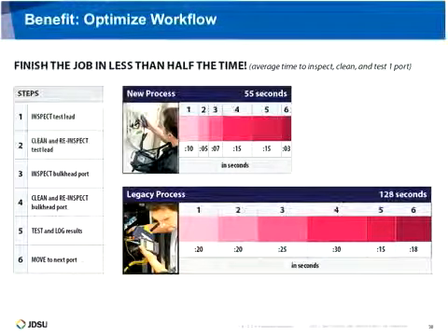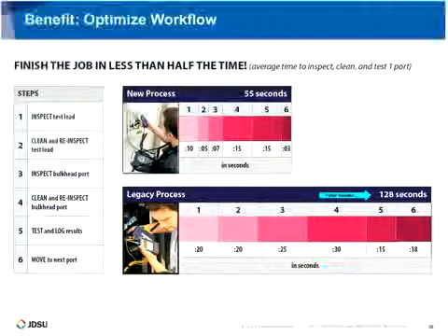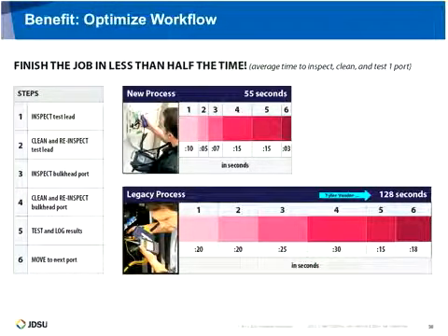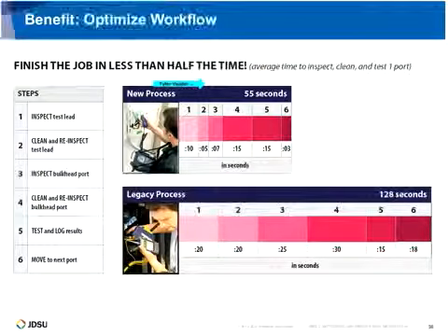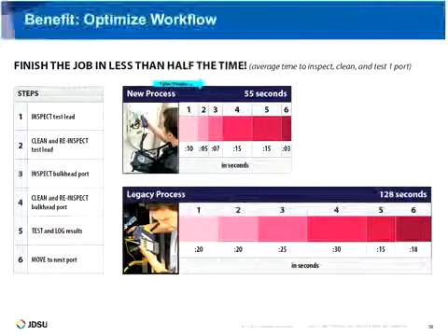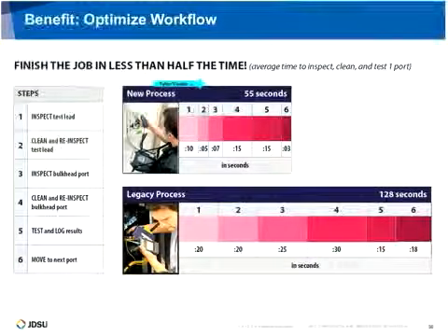The benefit of that, obviously, is that you can work a lot faster. The process that I described earlier of over 2 minutes, that's the old way of doing it. Contrast that with even a new technician being able to do it in less than a minute. We've got people who, even after limited exposure to this tool, are able to do an entire cycle of a connector, certifying it and taking the power measurement and everything, in 30 seconds. So a real benefit: 30 seconds versus 2 to 5 minutes per connection.